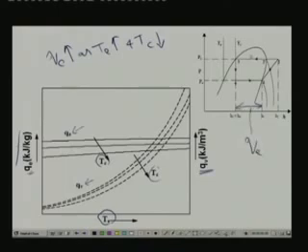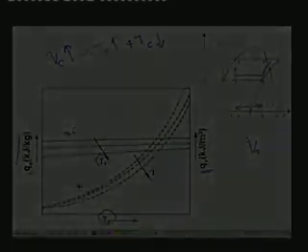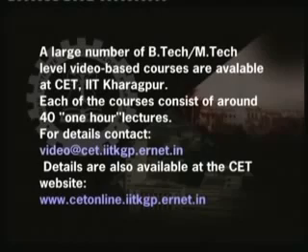Okay. So, if you are keeping the condenser temperature constant and varying the evaporator temperature, for example, I am increasing the evaporator temperature, that means this line shifts up. Okay. And you have the new cycle like this. So, the increase in refrigeration effect is very small. You can see, and you can see that it